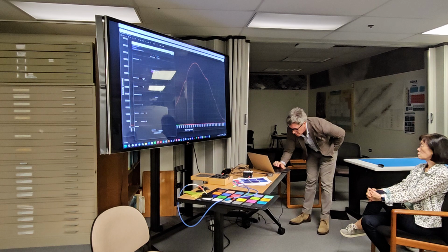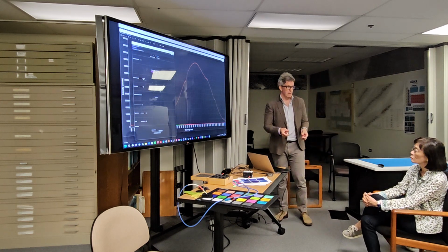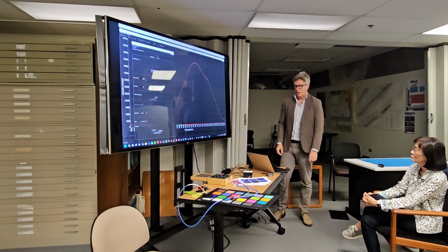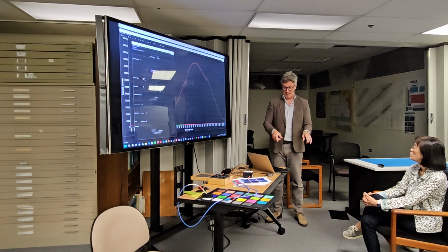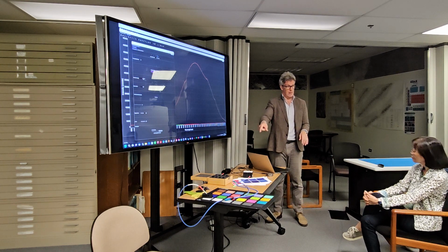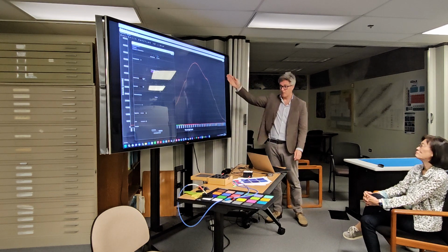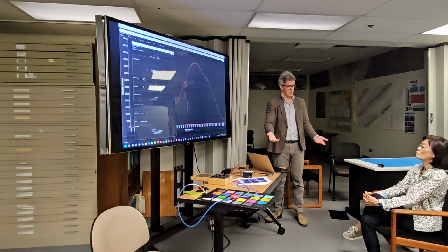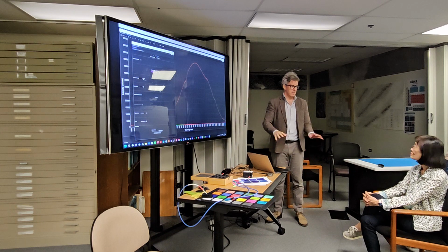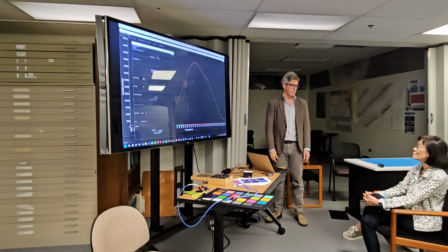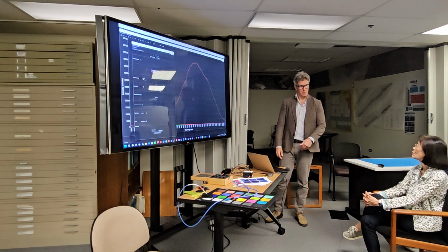Okay. This desktop spectrometer, these are used for things like production lines where they're making medical pills. One of the ways that they can monitor the purity of the pills is to pass them under a device like this and just make sure that the curve looks the same, looks the same, looks the same. And if the curve changes, that means there's a problem with the composition of the pills, which is being manifest as a difference in the reflected light. So that's one industrial application that these things are widely used for.